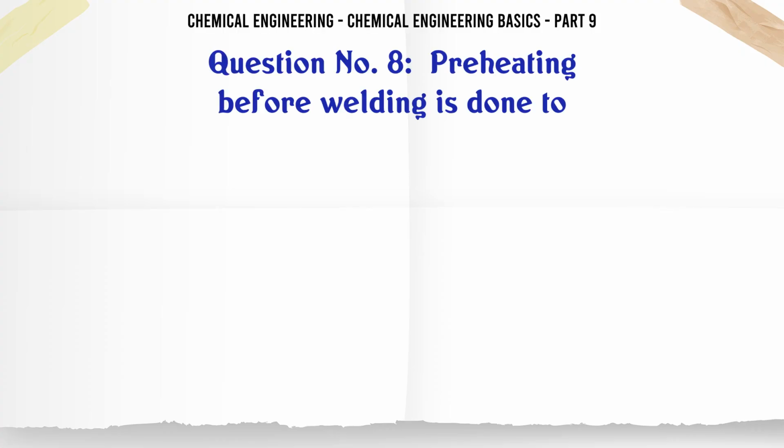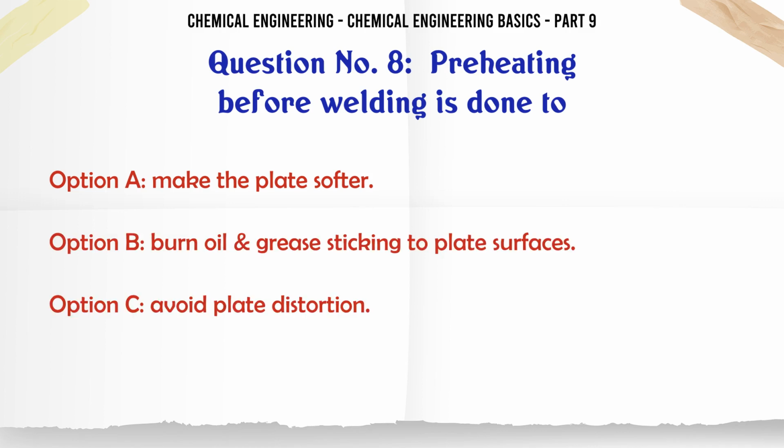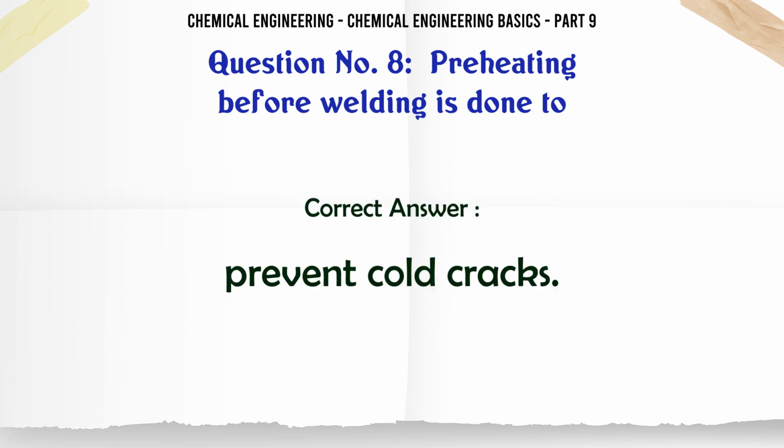Preheating before welding is done to: A. Make the plate softer. B. Burn oil grease sticking to plate surfaces. C. Avoid plate distortion. D. Prevent cold cracks. The correct answer is prevent cold cracks.